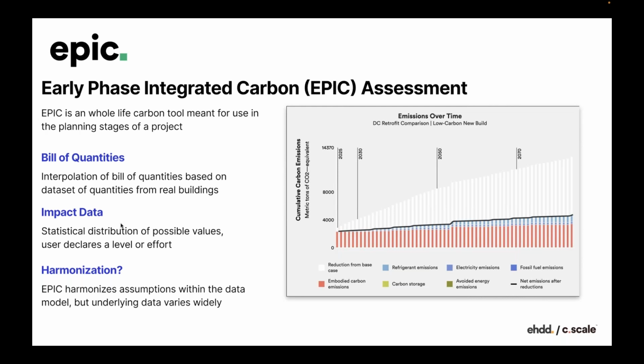So if you say you're going to design an envelope with a carbon intensity of 4 kg CO2e per square foot, there's a lot of different ways to do that, but we know from our data set that that is possible today. And then in your later design phases, using Tally and EC3 or One Click, you can really tease that apart to figure out the exact products to get you there.